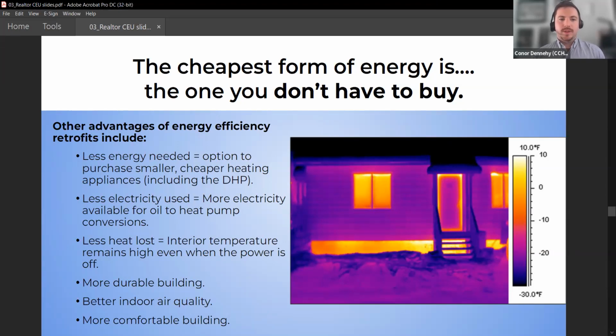It's really important for heat pumps because they're kind of sensitive equipment and they can operate really well with optimal conditions. But if you've got a house and it's not operating that efficiently, then somebody can bring in a heat pump and they might be a little bit disappointed with how the actual operation of it is going. So it's good to get out ahead of all of that and get in contact with an energy auditor for the house, do some air sealing, add some insulation, take a look at the doors, the windows, weather stripping, all of these factors.